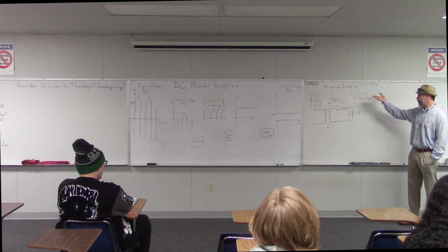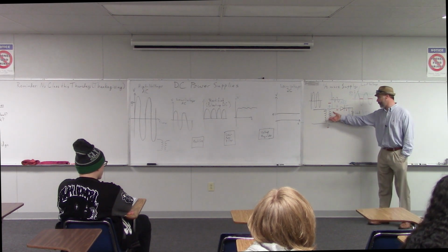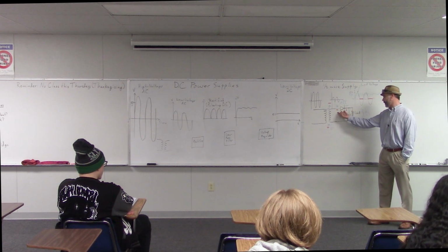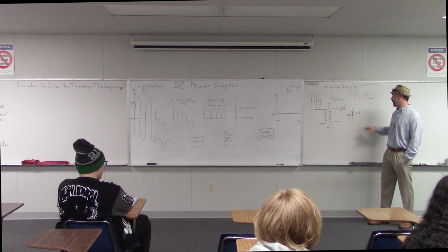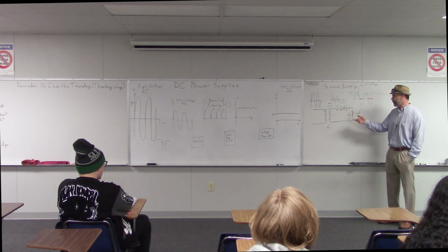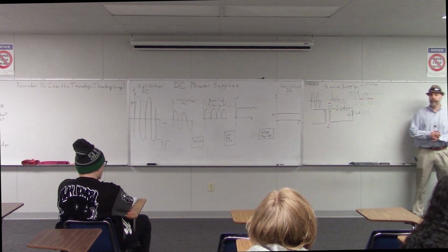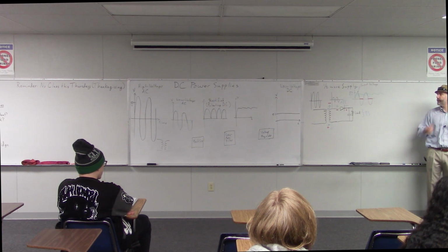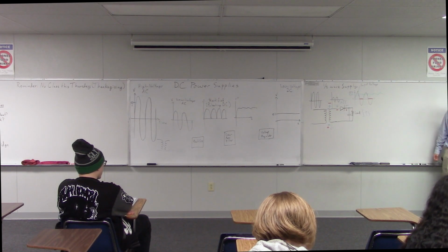So that's really what a half-wave power supply is. We have a transformer. The rectifier is just a diode. We have a capacitor to smooth things out. And then we could put a voltage regulator in, and then that would power our load. So any questions about the half-wave power supply? OK. Cool.